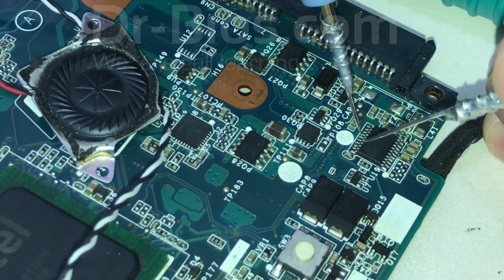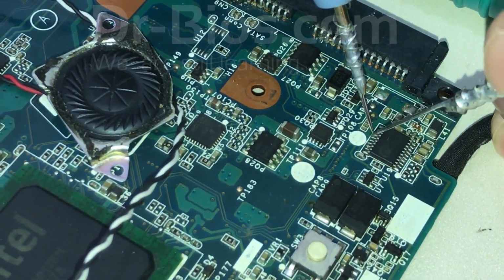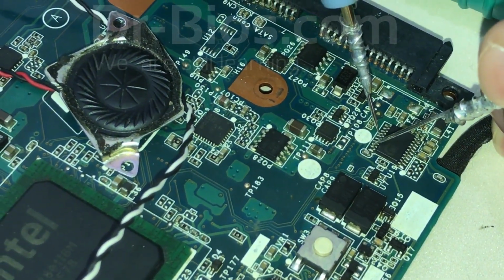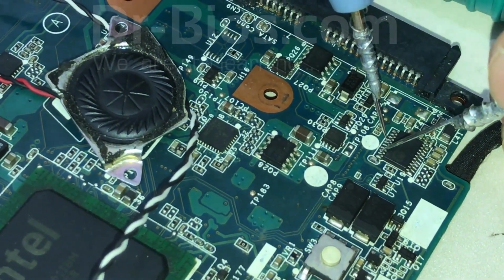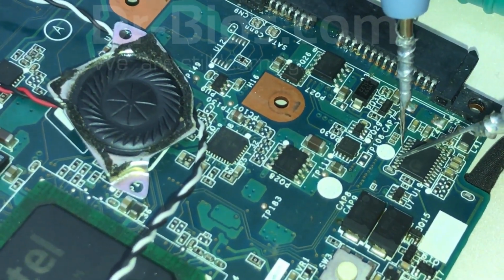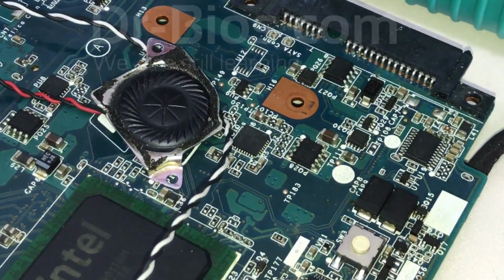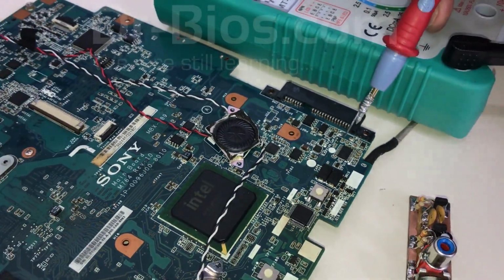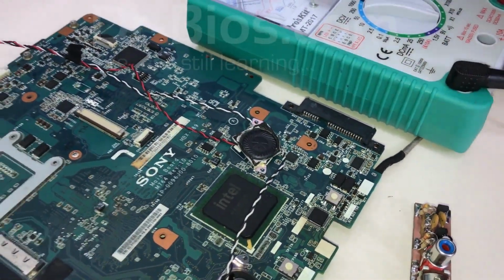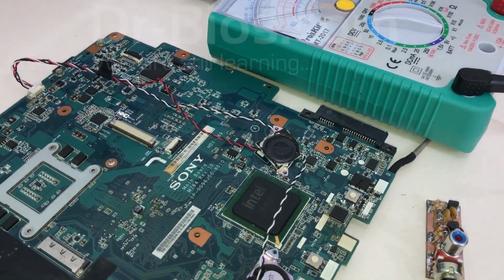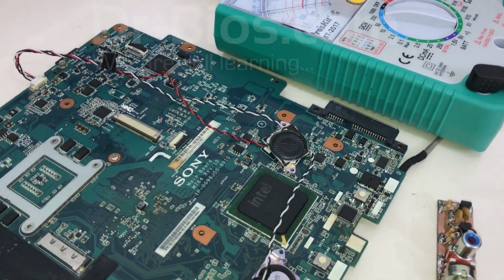Now I want to test the right speaker, pins 14 and 18. I place the probe on pin 14 and connect and disconnect the probe on pin 18. There is noise sound. Small noise. So in this way, with this test we tested the speaker, connector, and direction of the amplifier output to the speaker, and we realized that the direction is okay. Now I need to test the amplifier.